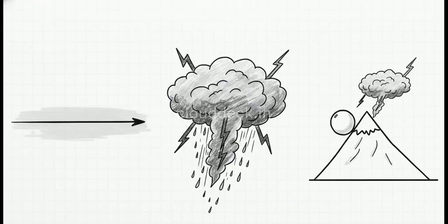And this brilliantly illustrates how these lapse rates actually dictate real-world flight conditions. So when the environmental lapse rate, which is just the actual measured temperature of the surrounding air, is less than the saturated rate, we have absolute stability. The air totally resists moving up, which traps haze and gives you really smooth, but unfortunately poor visibility flying.